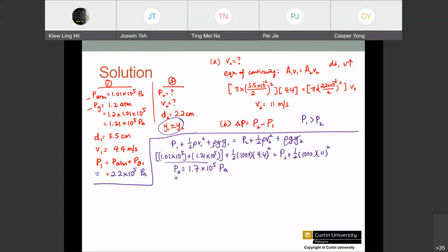So remember just now our V2 is higher than V1, right? So this is in line with the Bernoulli principle. When your velocity is higher, your pressure is lower. Okay. So P2 is lower, right? So now the question is, they want you to find the difference between these two points. So change in pressure. Wait.